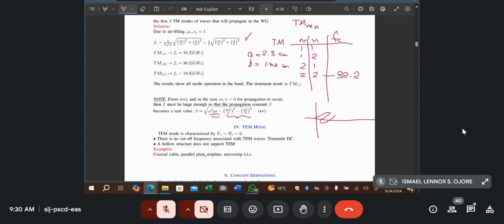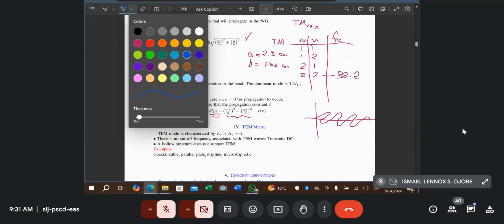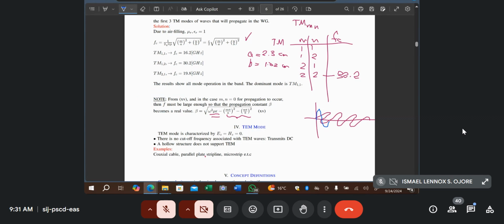You may want to transmit your waves in a horizontally polarized manner or vertically. In this way, using just one hardware antenna with two polarizations, you are able to transmit at the same time through what we call transmit polarization diversity. And if you want to transmit the wave through circular polarization, you may need an antenna which is helical to do that.